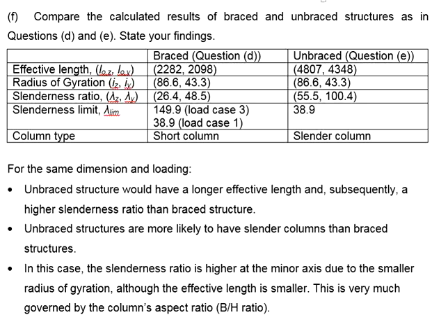In principle, slender column will have additional second order moment. And because of this second order moment, the moment to be taken by the column will be relatively larger than the short column. As a result, you might need more reinforcement bar as compared to the short column. In practice, steel bars are more costly than concrete. In terms of the calculations, slender column will be more tedious than the short column.